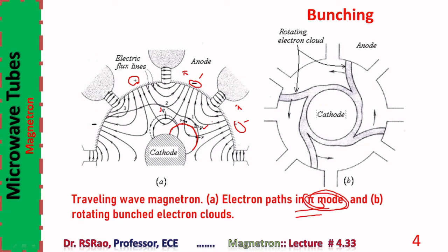In the presence of RF, its path gets altered. It travels like this. Notice while it is traveling in its path, it faces opposition to its movement from the RF field. As its movement is opposed by the RF field, energy transfer takes place from the electron to the field. So the electron gets somewhat decelerated, but it continues traveling like this.